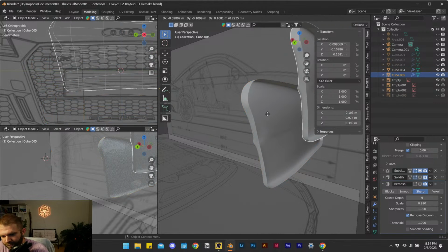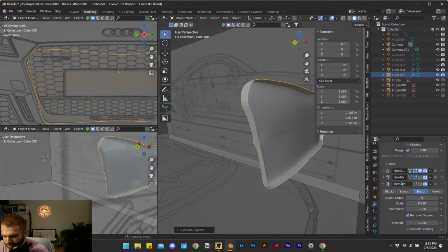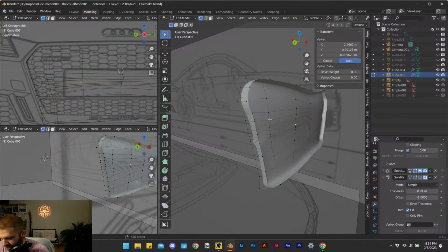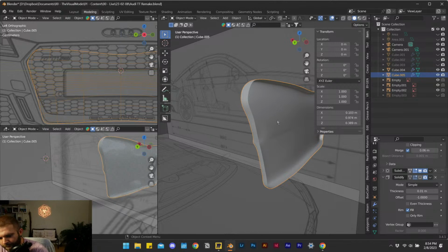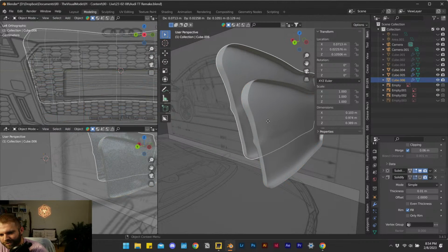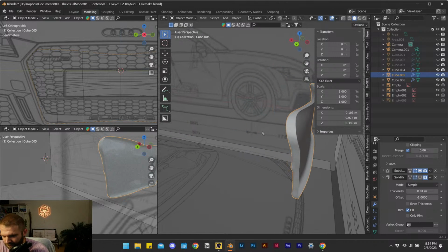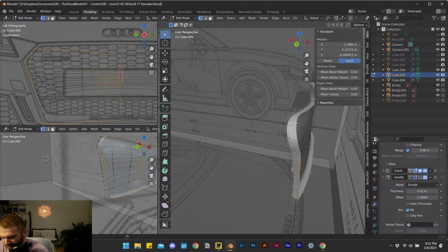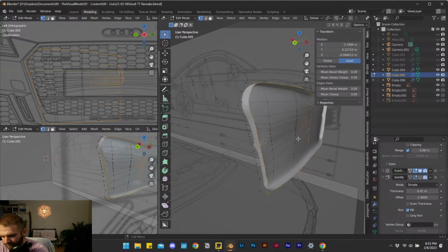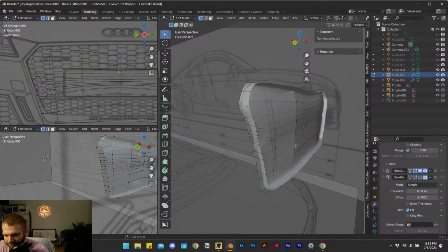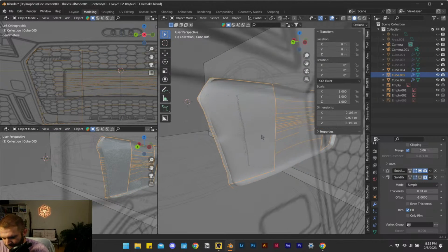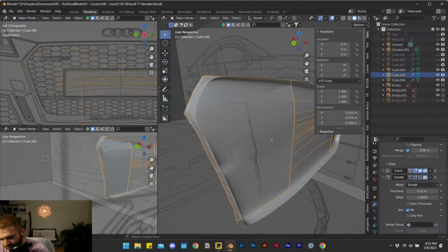So Shift D, not turn off solidify, but actually just eliminate an edge here. No, actually, yeah, what I wanted was the previous version of this geometry. Because as I extruded these points, I now want to eliminate all these points on this face, delete faces and edges, so that I get that original.